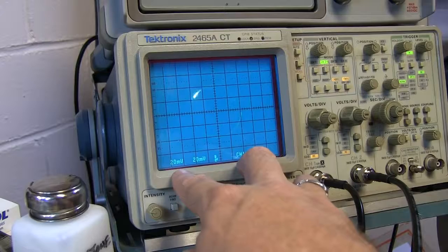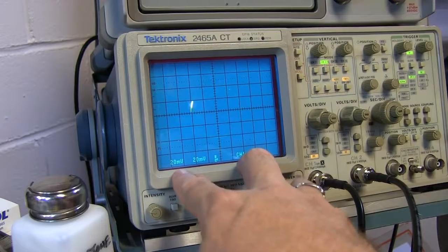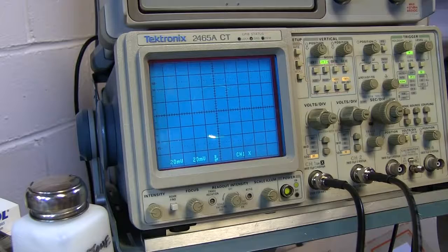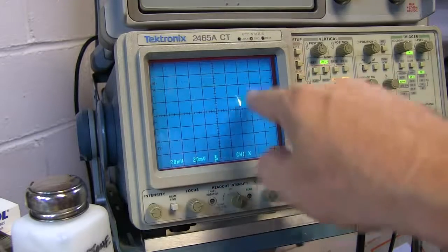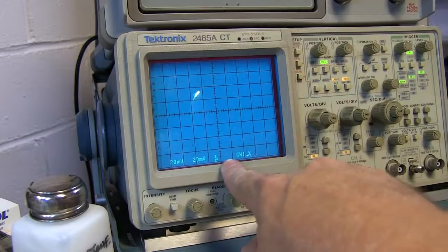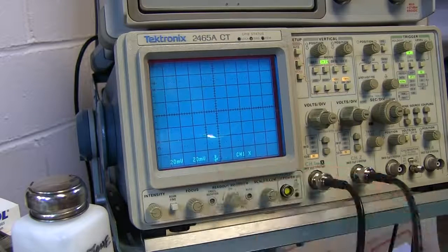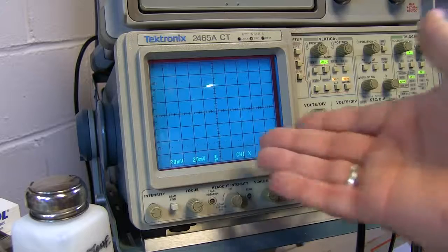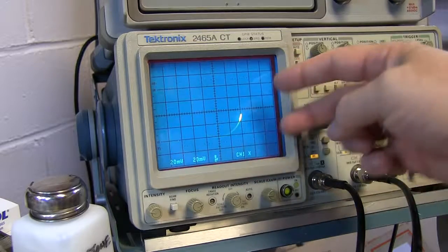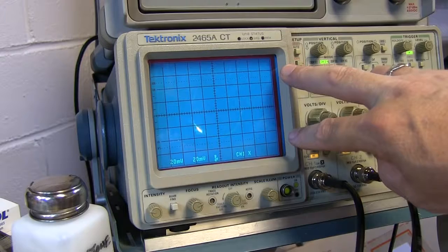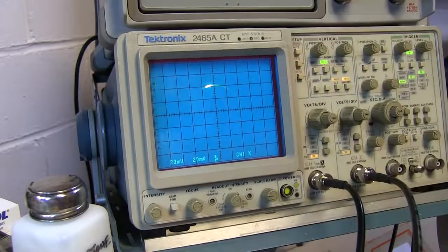So if I dial in a 180-degree offset into one of those, now we can see the vector spinning in the opposite direction. So when it's spinning in this direction, for example, this might represent that the RF signal is now 1 hertz below the local oscillator frequencies, and in this situation it's 1 hertz above. So we can introduce a frequency offset in one direction or the other by simply changing the phase between 0 and 180 degrees, and essentially it's just inverting or not inverting one of those quadrature local oscillators.